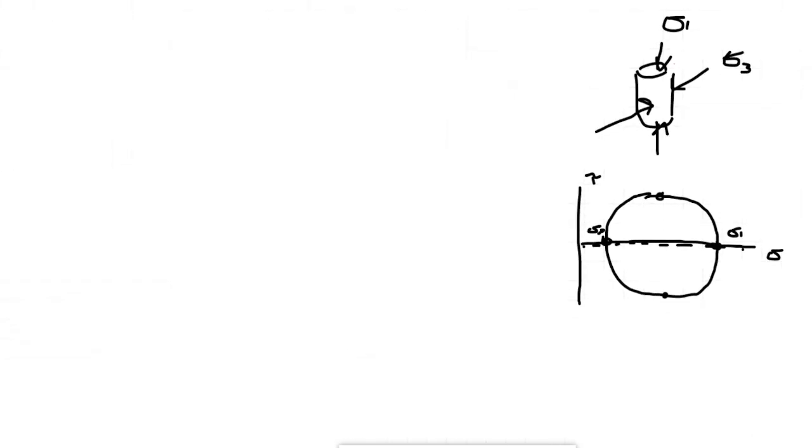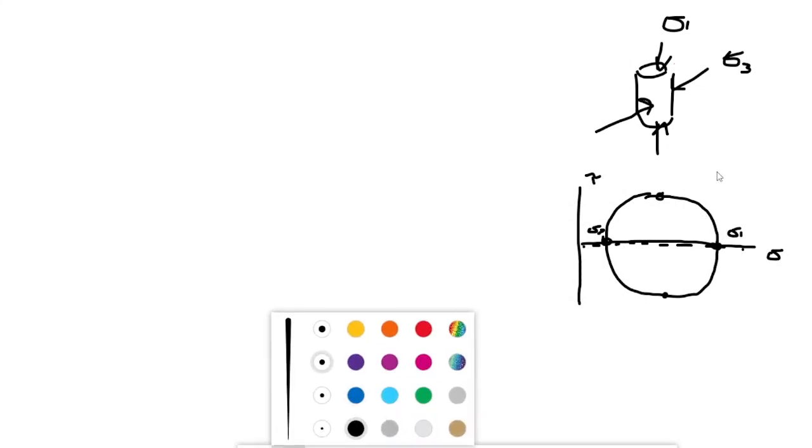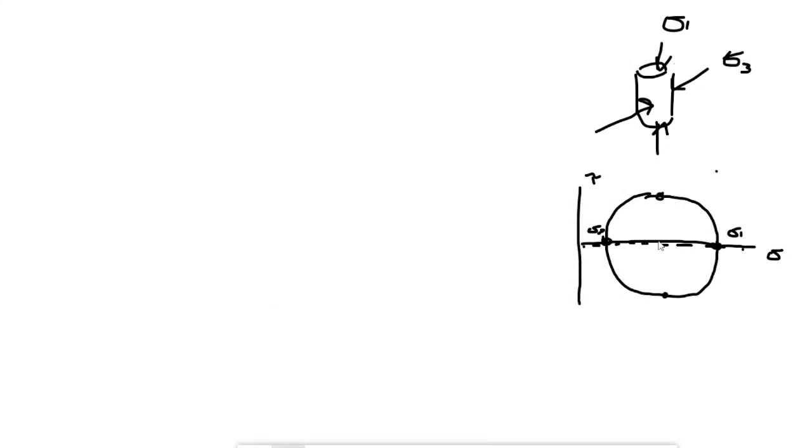So the point is, once we're able to think about rotating these axes, we're going to start changing it. Say, all of a sudden, instead of being right along the x-axis there, we've rotated a little bit. The maximum normal stresses we've incurred have decreased, but all of a sudden we're experiencing some shear. And what if the rock is weaker in shear than it is in compression? In fact, what we find most of the time is that rocks in confinement are failing along shear planes, right?